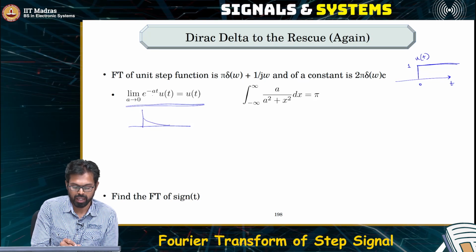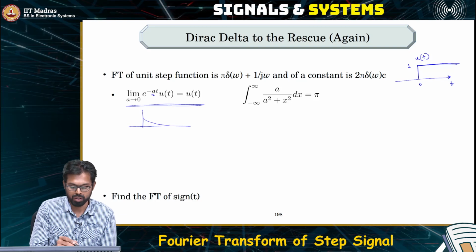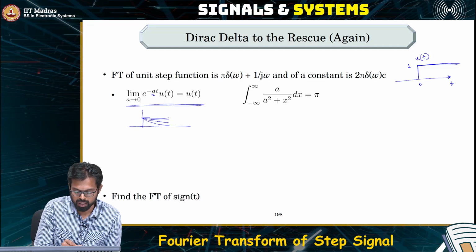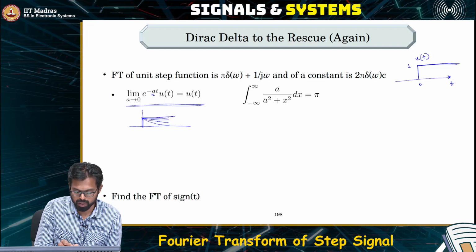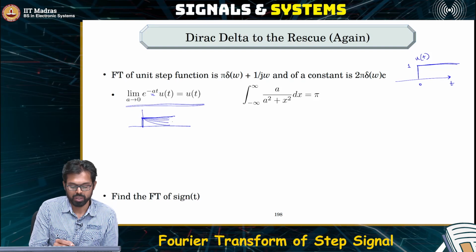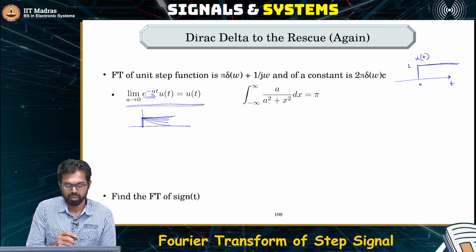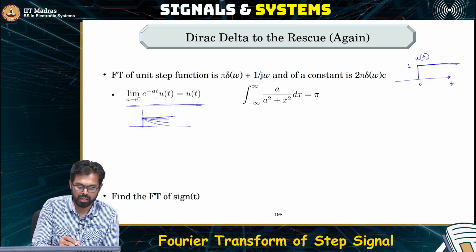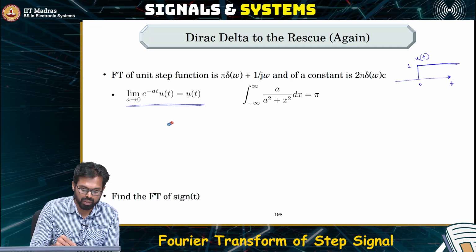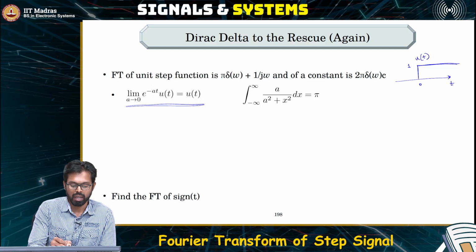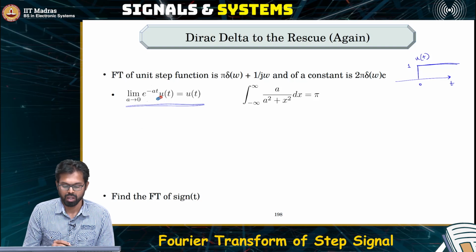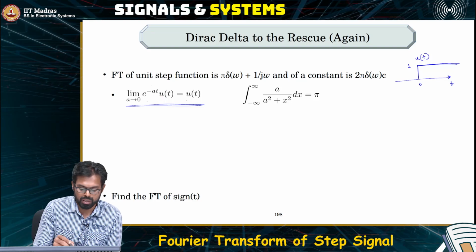As the exponent becomes smaller and smaller, we have a signal which keeps changing, and eventually for the exponent a equal to 0, if you substitute a equal to 0 here, we simply get 1. So this entire signal would look like just a unit step function. We are going to consider this as the limit of such a set of functions.